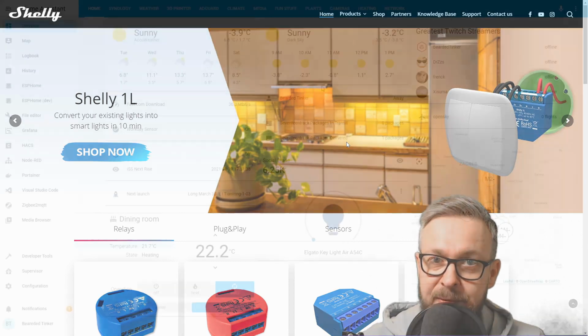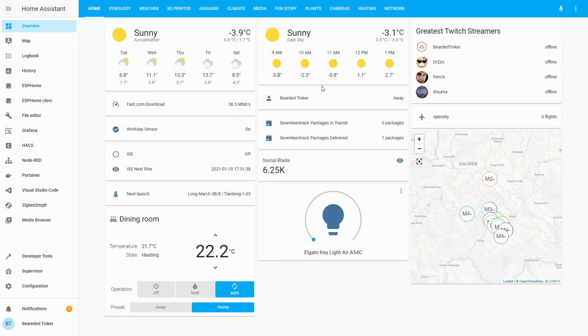So let's get started. The presumption for the next step is that you have your Shelly device already connected to the electricity, that you connected to it via Wi-Fi and configured your Wi-Fi connection or Wi-Fi SSID, and also that you configured either the DHCP, which is the default one, or the static IP address. When you finish configuring your Wi-Fi, your device will disconnect and reconnect to your Wi-Fi network, and then you will be able to access it with the predefined or DHCP IP address.